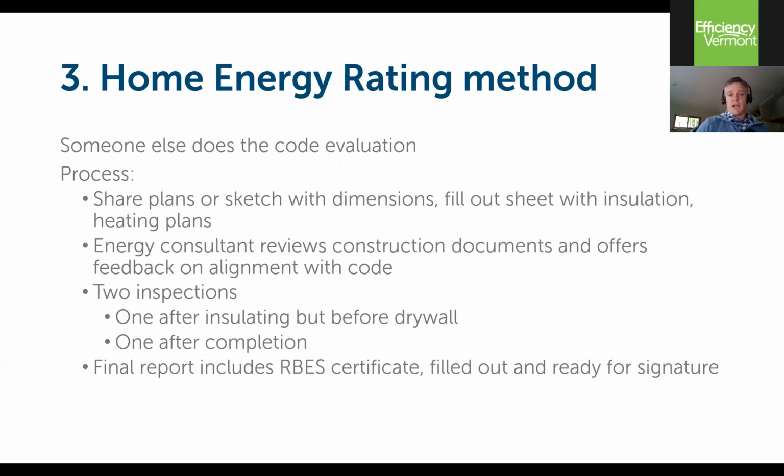And finally, the third option is using the home energy rating method. So you're working with a third party who is going to review the design for the building and do some preliminary modeling and evaluation to see if the proposed design will meet the intent and requirements of the code.